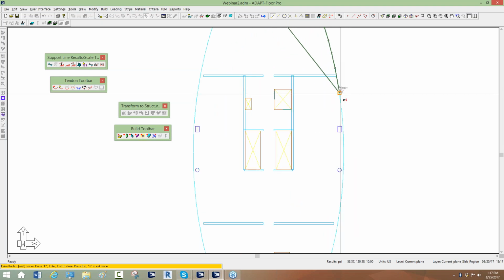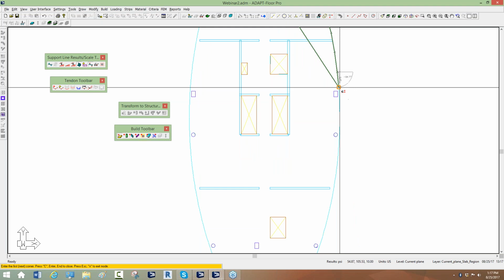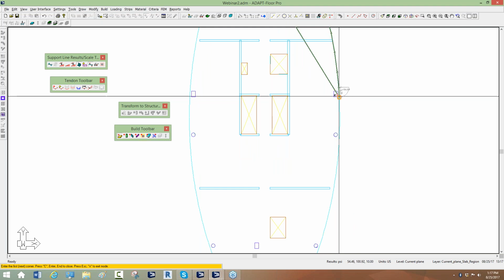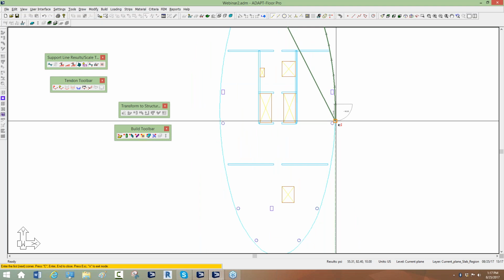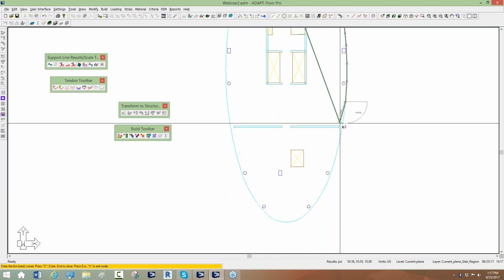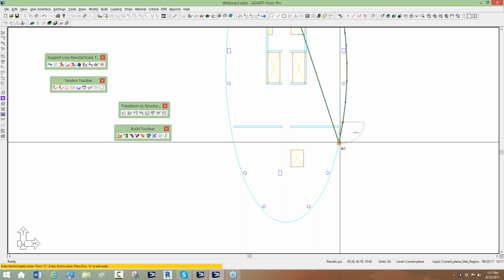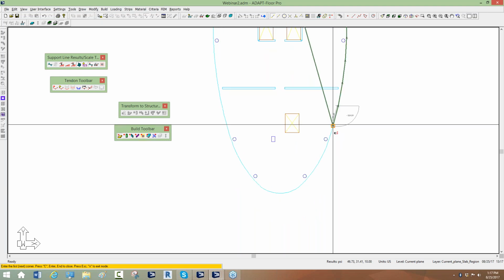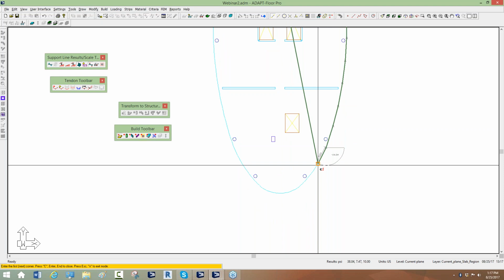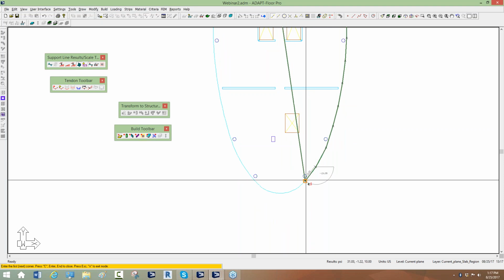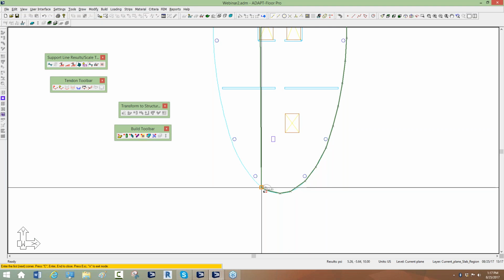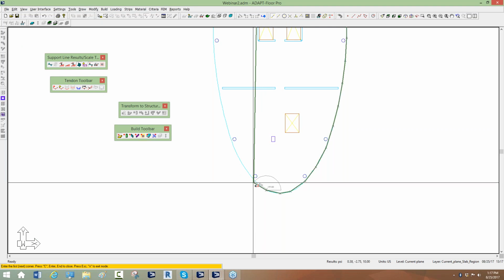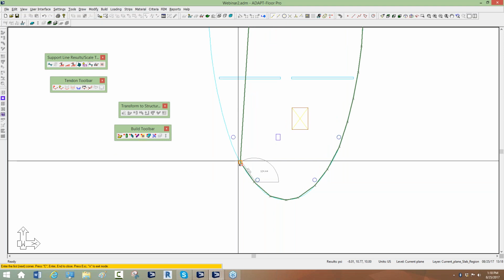So what will happen is your mesh could get much tighter than you may want it to be, because instead of having 20 or 30 points defining the slab using these linear segments, you have 300 points defining the slab, and the mesh is dependent on those points which define these closed regions like slabs, openings, and drop panels, thickenings, etc. So let's go ahead and continue around this loop here.